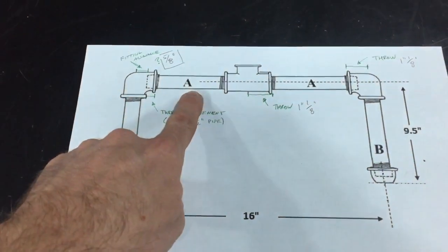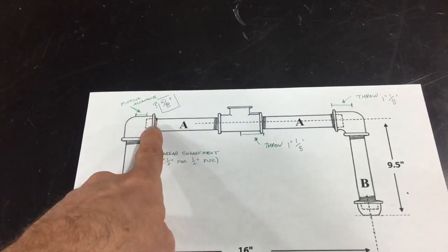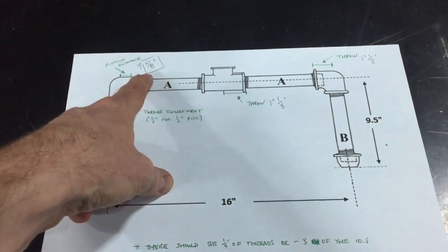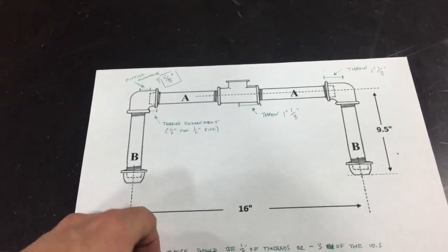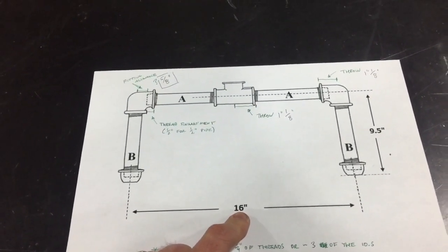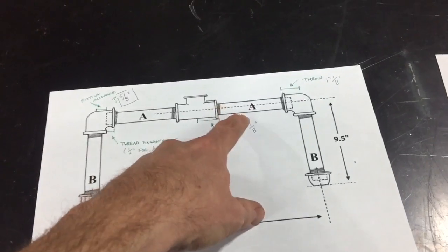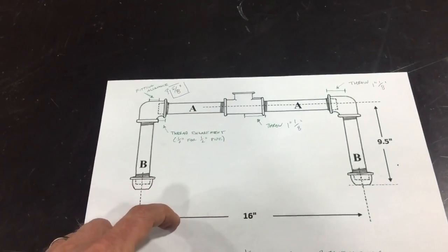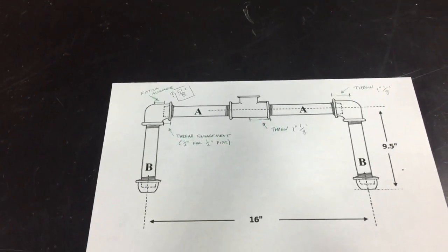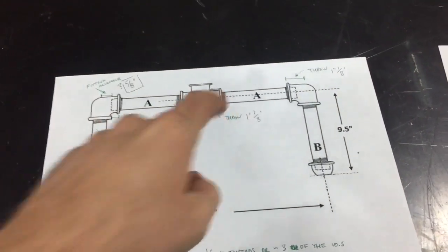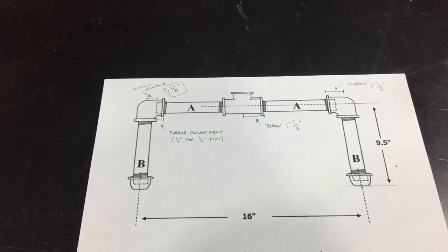All right, so I'm just about to cut this nipple here, this piping piece of pipe, and we need to subtract from the 16. We need to subtract 5/8 4 times. So that ends up being 2.5 inches. So 2.5 inches off of 16 puts us at 13.5. So 13.5 inches, and we need 2 of those. So 13.5 divided by 2 puts us at 6 3/4. So we want both of these to be 6 inches and 3/4 of an inch. So we'll go ahead and cut our first chunk of pipe there to 6 3/4.